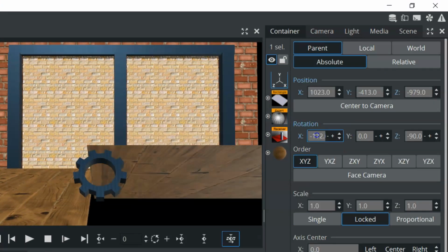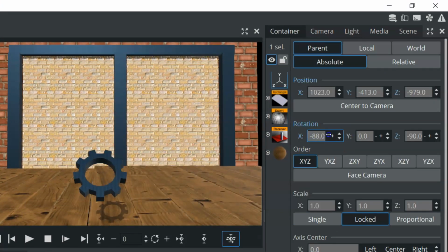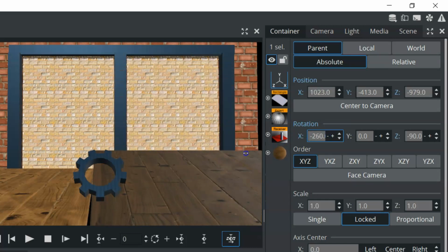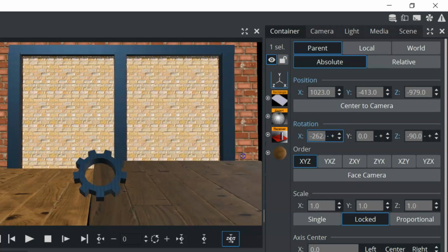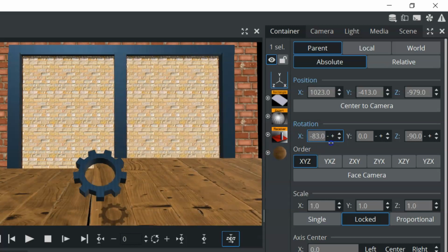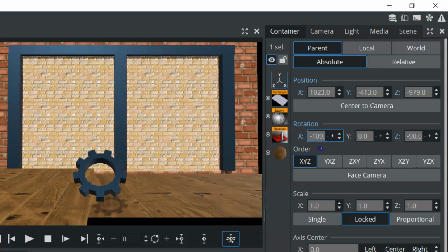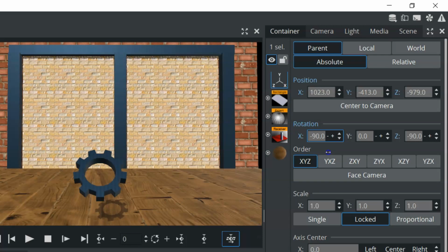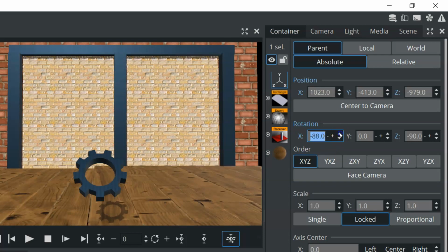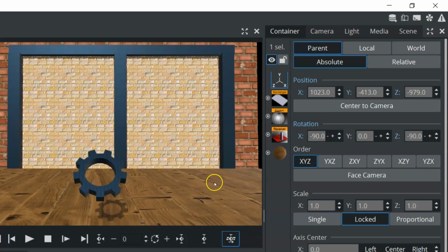And as we rotate our rectangle around, one side we can see the shadow, the other side we cannot see the shadow. So just make sure that your faces are facing the correct way. In this case, one is 90, the other is -90. So just make sure that if it is a 2D object and you have a receiver on it, that it is receiving it on the front face of that object.